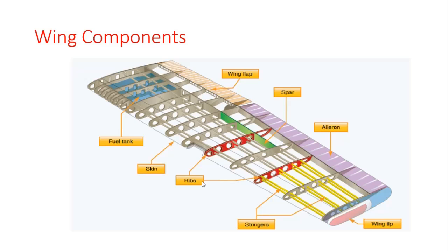They are attached to the rear or trailing edges of the wing. Two types of control surfaces are referred to as ailerons and flaps. Ailerons extend from about the midpoint of each wing outward toward the tip and move in opposite directions, to create aerodynamic forces that cause the airplane to roll.